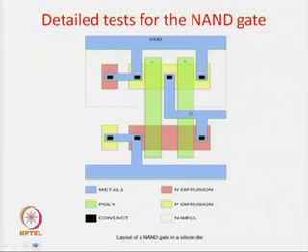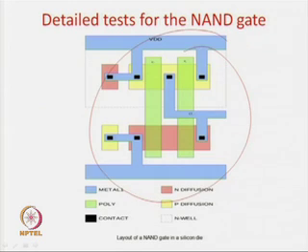So, that was about the transistor level design, but now how is a transistor designed? The transistor is designed when you lay it out in a physical backend, or in a VLSI circuit. Your single NAND gate generally looks like this. This is your metal, this is your N diffusion, this is your poly. So, this is the physical layout of your circuit.